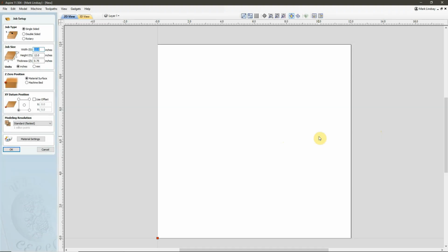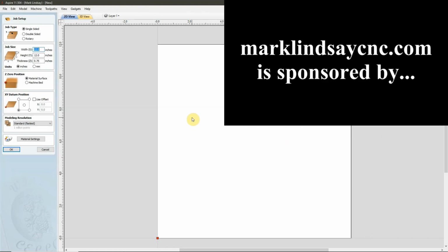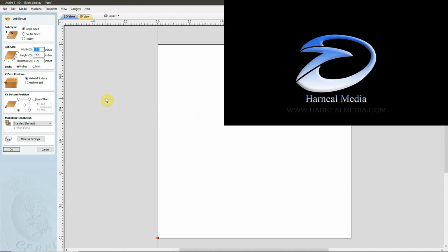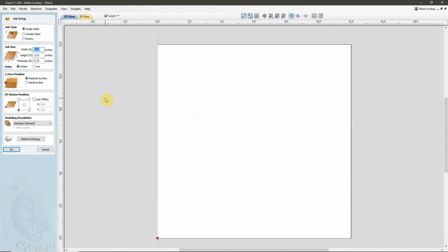Hey y'all! In this video, I'm going to get into probably the most popular question I've been getting over the past year, and that is the difference between setting your Z0 position to the material surface or the machine bed. Now, even though I'm using Aspire version 11.5, this is true for all of the Vectric software titles.